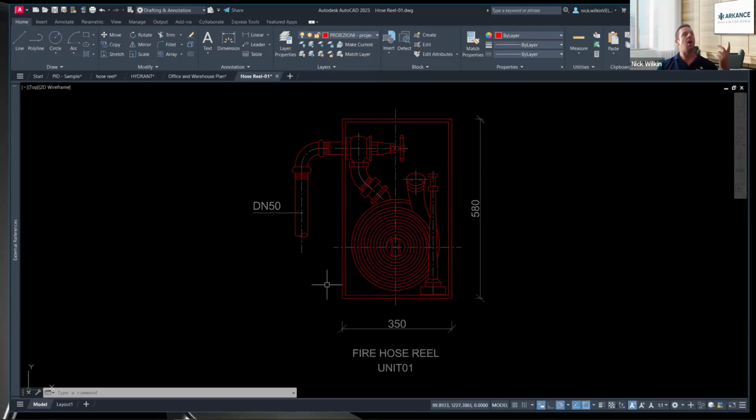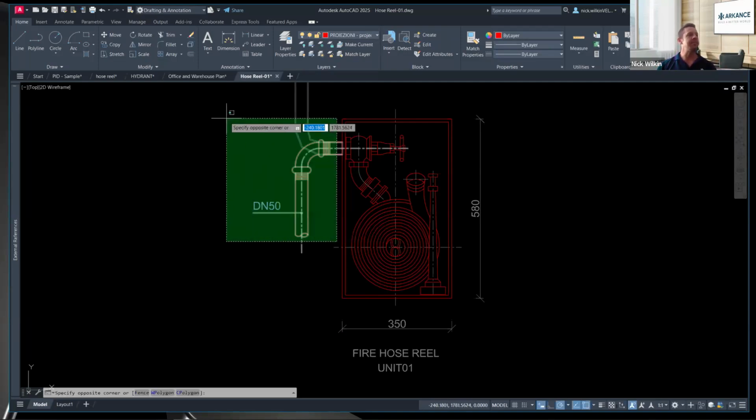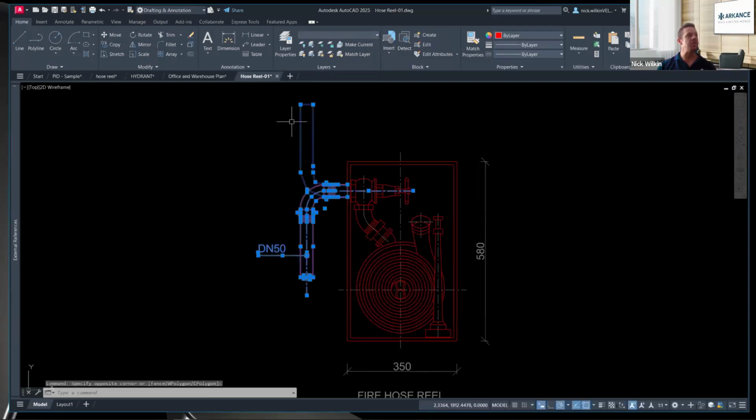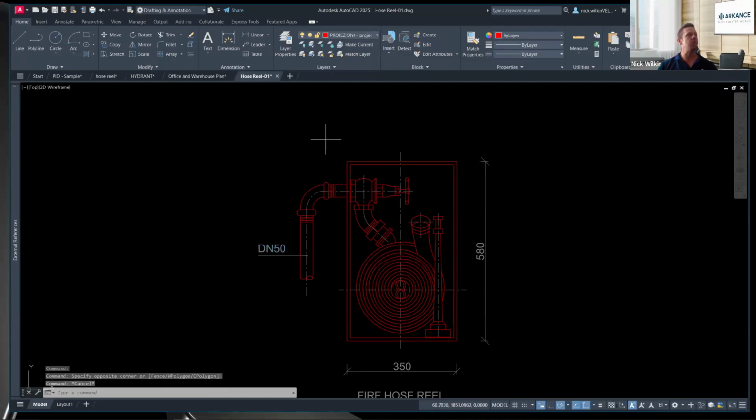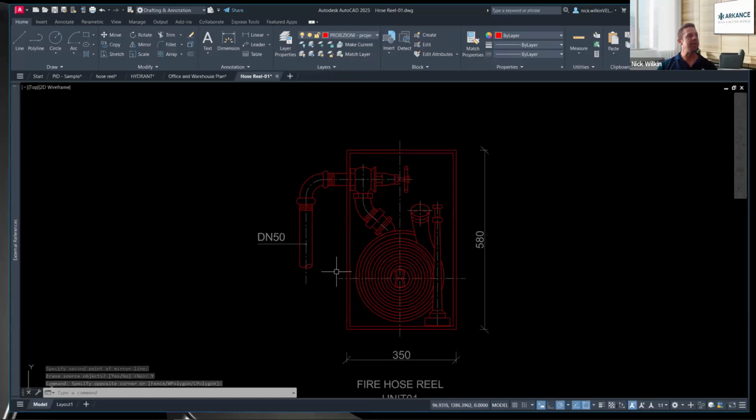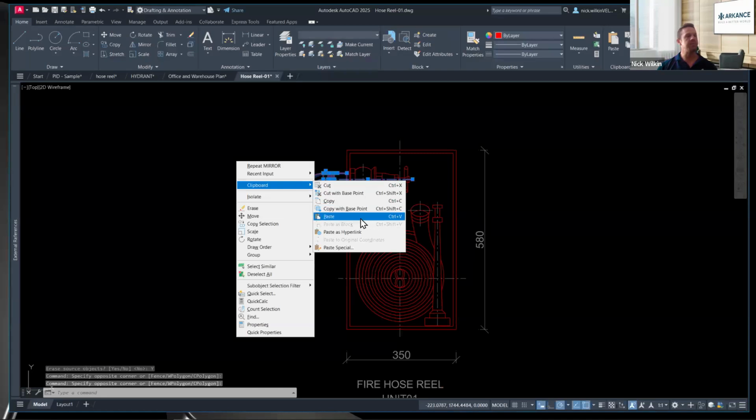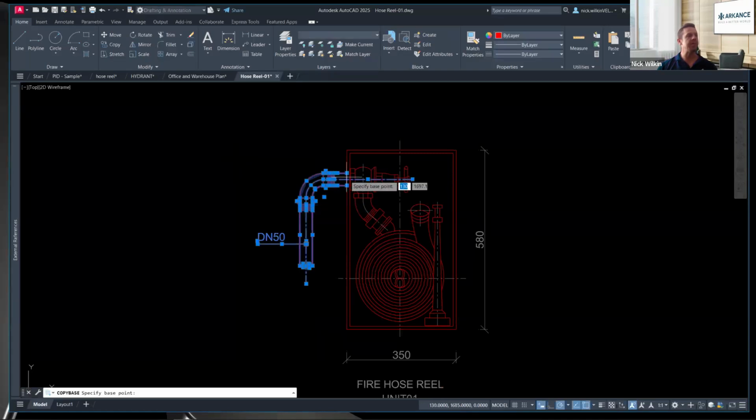But obviously, if you know AutoCAD, I'm going to keep it simple. You'll see here that this is mirrored, and I've actually got a whiteout over here. This whiteout hasn't been changed. I'm just going to mirror that one if I can. I'm not sure if it'll allow me to. Let's see if it does. Yeah, it did. So that's all good. Now what I'm going to do is copy this change, copy with base points, go over to my actual drawing. You could now do a drawing compare.